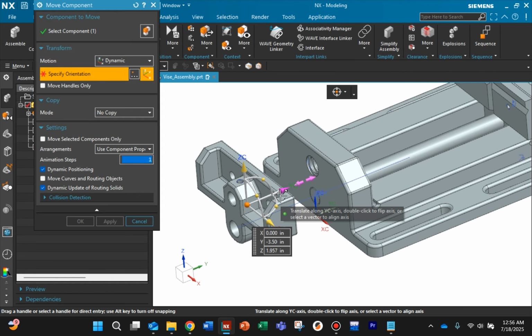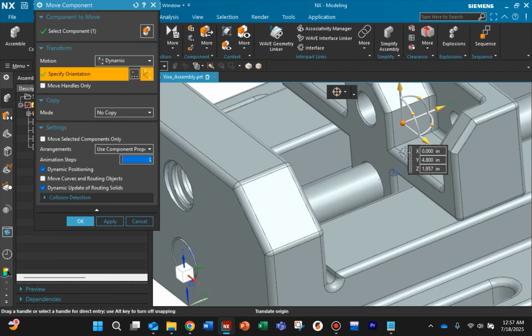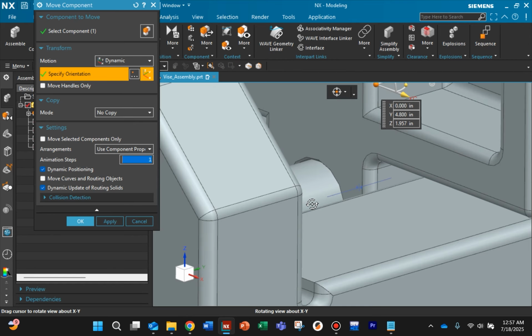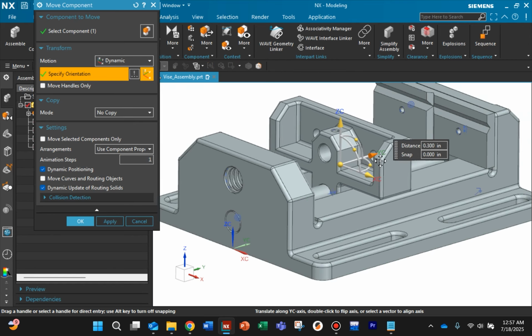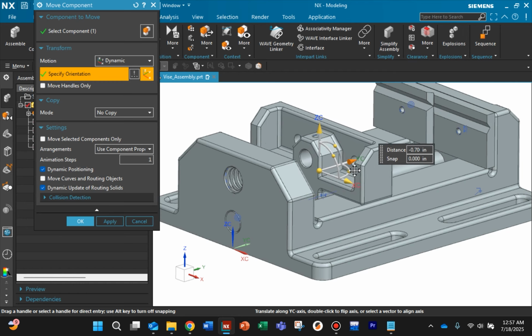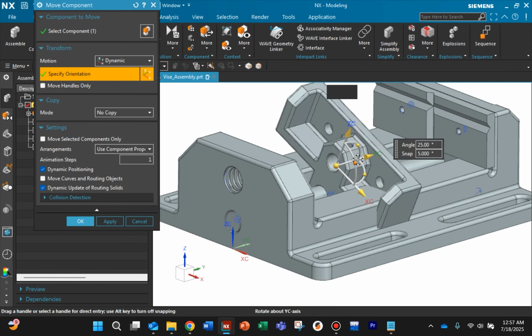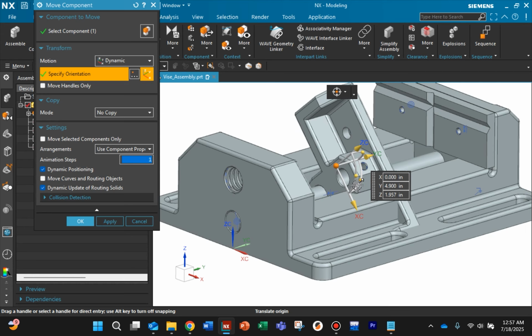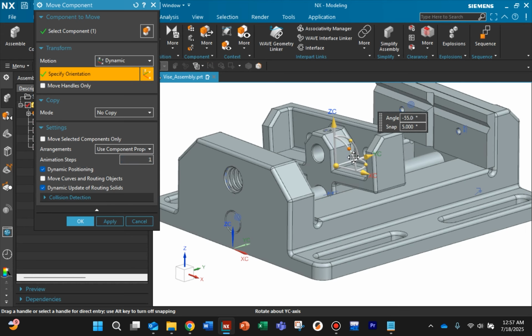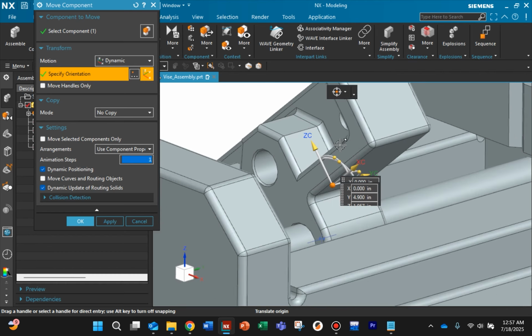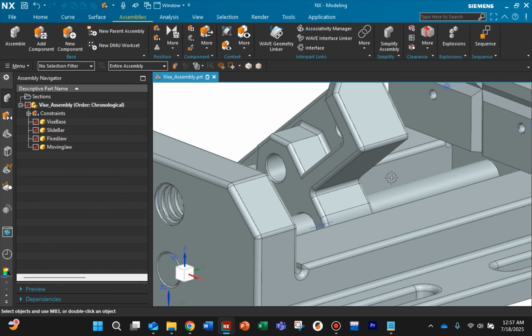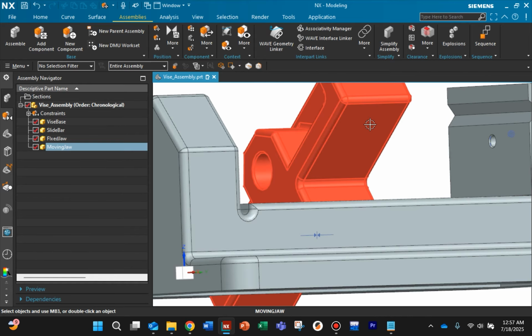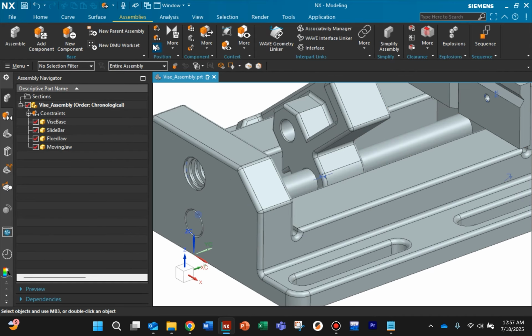Now go and move the jaw, and notice it's located correctly. I can move this along the bar here, but we do have a problem because it can still move into the vise space, and that's not correct, right? That's not what we're looking for. I'm going to angle it slightly so we have access to this bottom right here, and we'll show you what we're going to do.